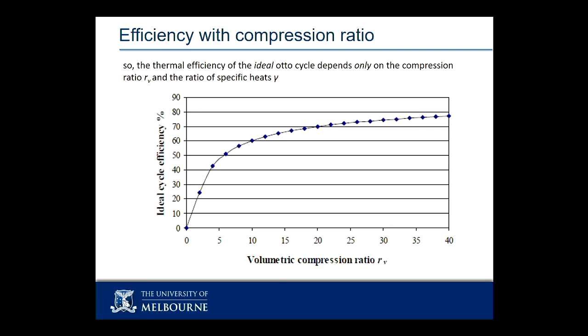I want the combustion to be nice and controlled after I've hit top dead center, to happen almost entirely at that constant volume. Bang now, but not an explosion, and not an auto-ignition, a burning flame front, and then release that energy through the pressure. So knock, this pre-ignition, this auto-ignition, will destroy an engine and make it undrivable.